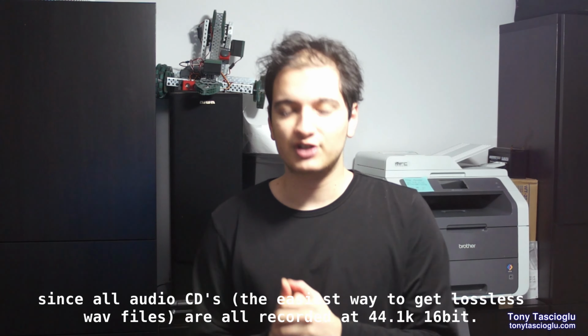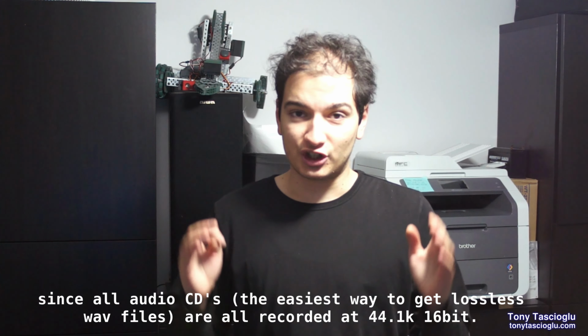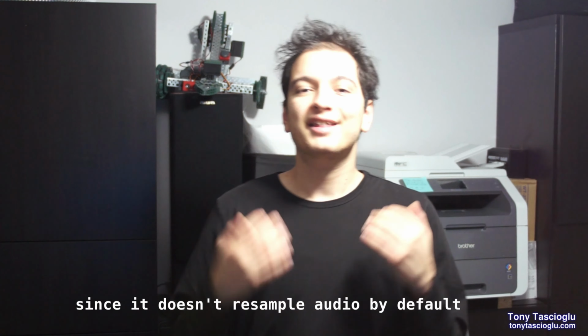Basically, the impulse recordings that they ship with SSR are recorded at 44,100 Hz, which is fine, except that means that your JACK server needs to be running at 44,100 Hz as its sampling rate. The problem is, most sound cards only support 48,000. I tried a Creative Sound Blaster SP0410. I also tried a pair of Sennheiser PXC 550s with a built-in DAC. And I also tried the motherboard's onboard audio. None of these could actually set the sample rate to 44,100. All of them, except the motherboard onboard, got stuck at 48,000.